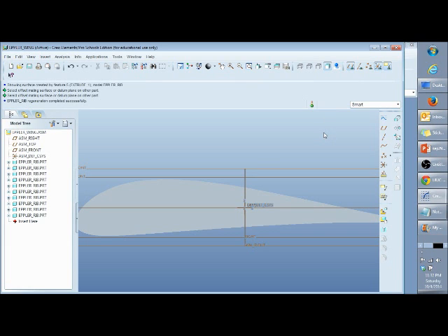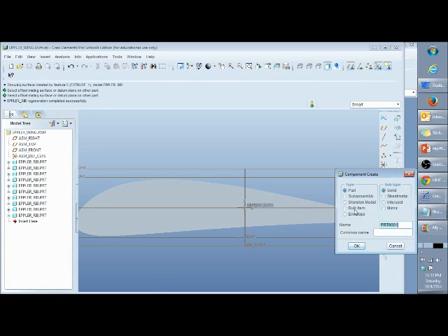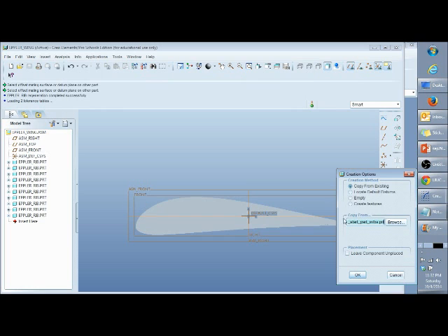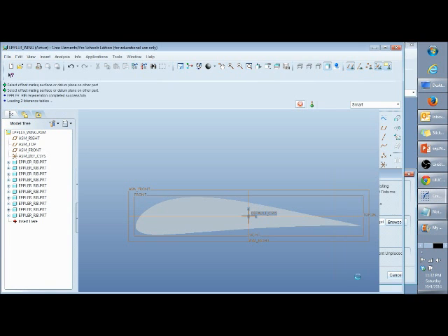What I'm going to do is not create a separate part and then bring it into an assembly like before, but create a part within an assembly. To do that, you click the button right here, which is just below that assemble button before. It'll ask you to create a file for it. So I'm just going to create a part, type part, subtype is still solid. Let's just name this spars. This will ask you what things to copy it from. Don't change any of this stuff. It should be good. Just go ahead and click OK.